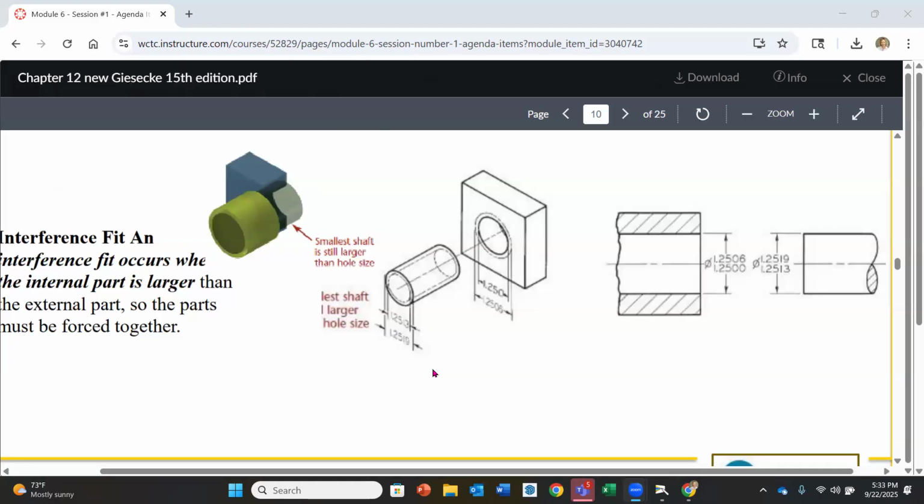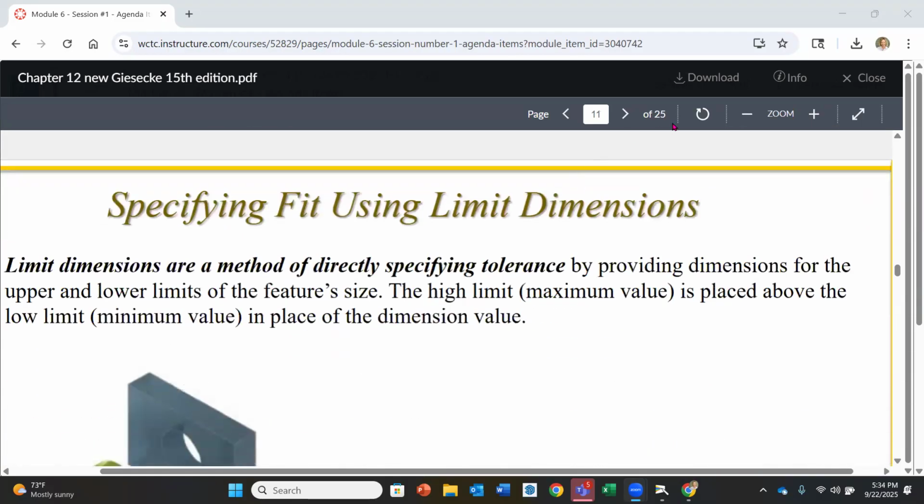So it's really the final function of what you're going to be looking at and how that's going to affect things. We didn't need a huge life out of the lawnmower tractor or the lawnmower hub bearings as opposed to our high-speed wrapping equipment. So know your application, and you're going to see differences in those tolerances and what's appropriate.